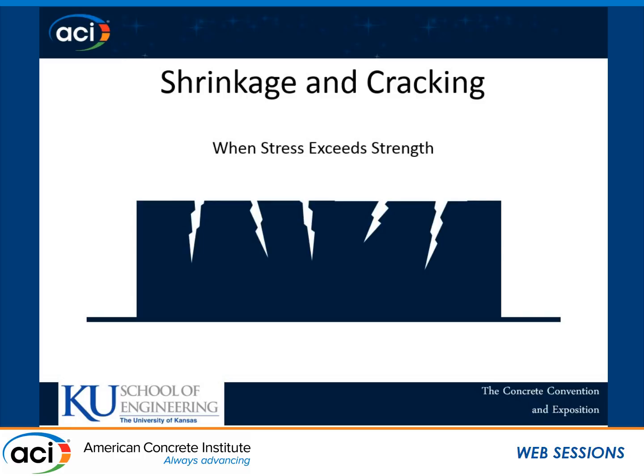At any point in time, if the tensile stress caused by restrained shrinkage exceeds the tensile strength, we'll have cracking. And it's not hard to imagine that the deformation of concrete is more important at early ages, because concrete is weak at early ages, and the tensile stress needed to crack the concrete is much lower compared to when the concrete is better cured.